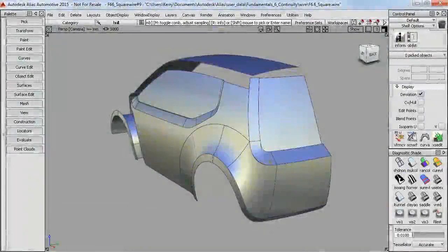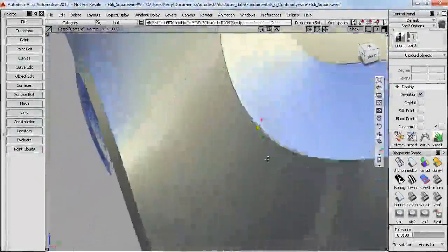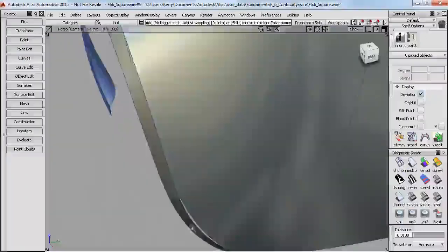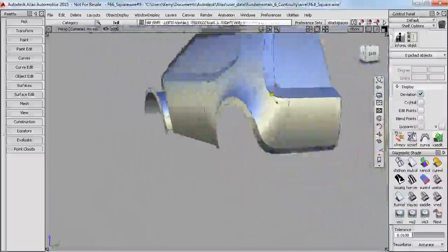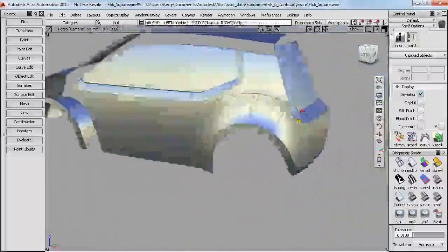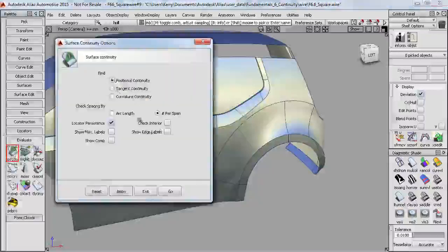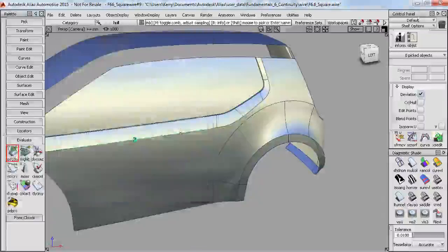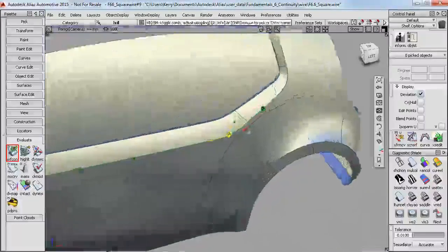In the previous tutorial, we ended up with obvious gaps between the freeform blends, as they only align to the two edges that you pick. So for example, that wouldn't stitch together for a prototype model. But those ones were obvious to see. Up here, where I've taken off the fillet, we needed to use the continuity check to show that the long sections are positionally continuous, but the blends failed.